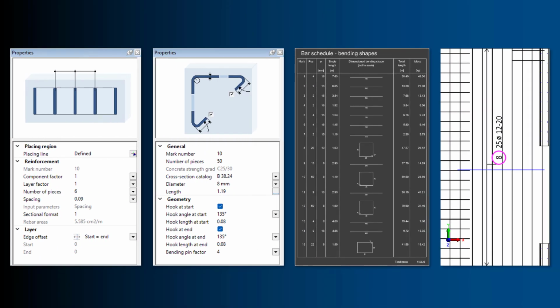In other words, the reinforcement calculated and designed in FEMDesign can be used as parametric editable objects within Allplan. Thus, for example, we can change the position and distribution, supplement them with hooks, list them in detail, and label them according to unique rules.